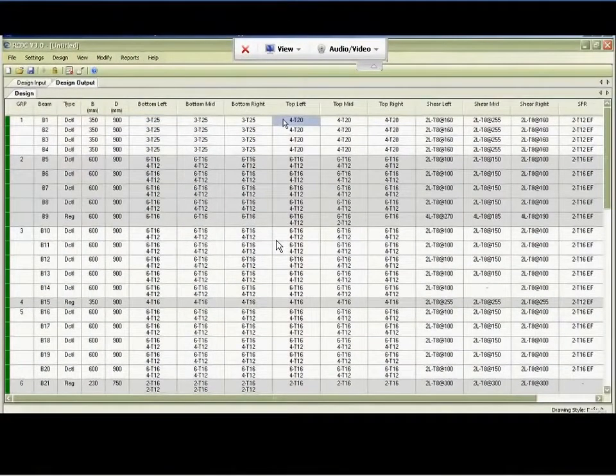The moment I do that, the software will detail with the information that we provided. So here you can see all the bottom gets detailed with 25, top gets detailed with 20 as required. So that's why we didn't specify a number. So it's evolved a number as per the requirement of the detailing in itself. So you can control detailing across a section or across an entire beam group using these tools.